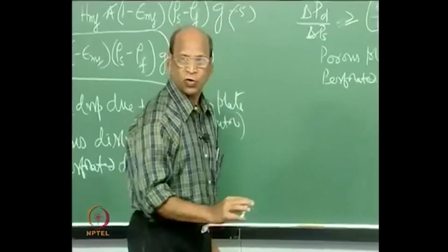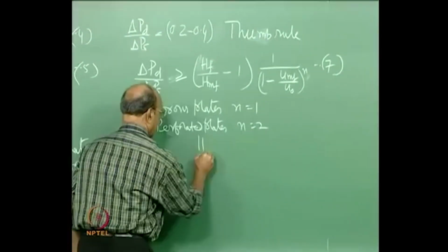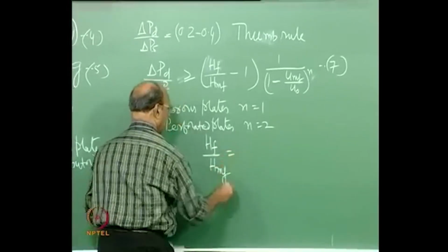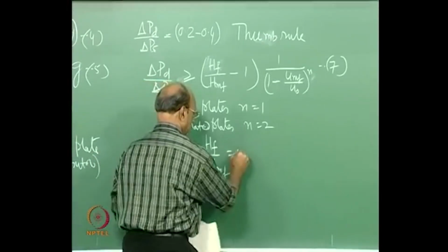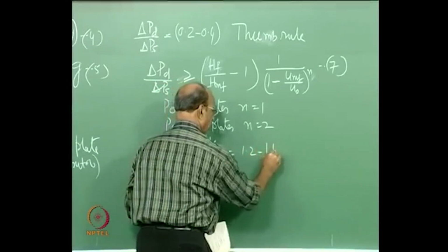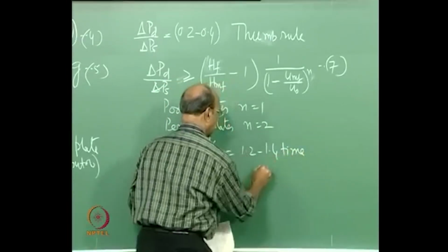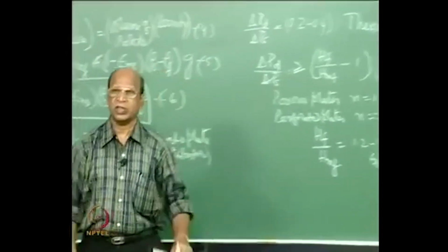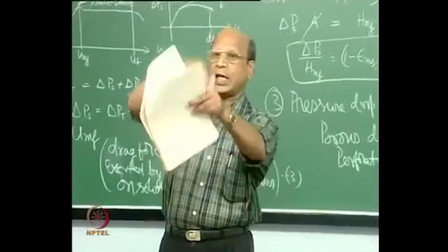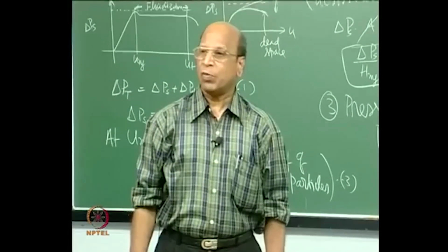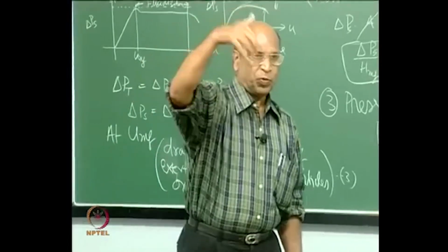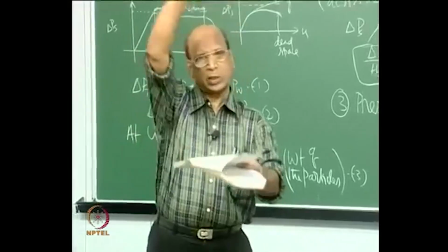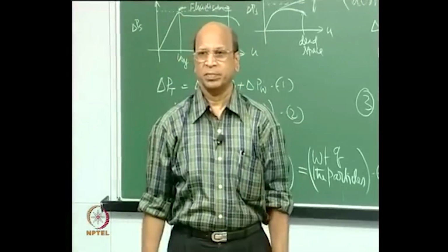Many times in the industry it will be 1.2 to 1.4 times for gas solid beds, where you have bubbles and all that. It cannot beautifully expand. It will expand only when you go for velocities beyond terminal velocities. Then it starts expanding and comes out of the bed.